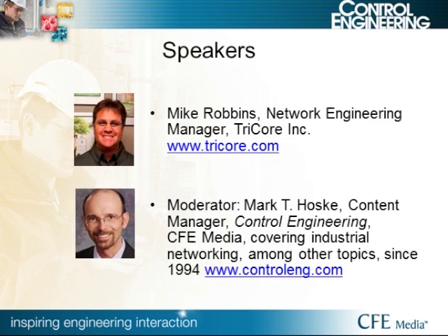If you've got a SCADA network, where you've got some HMIs getting information from the PLCs, you can use an unmanaged switch for that. But if you're using a control protocol over Ethernet, you would want to use a managed switch. The other thing is, if you're having a problem on your network and you need to go in and look at the switch, you can only do that with a managed switch.